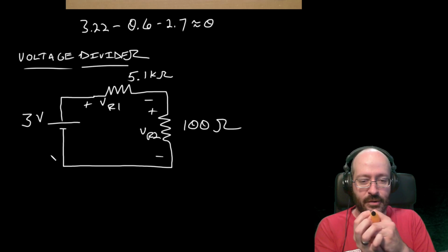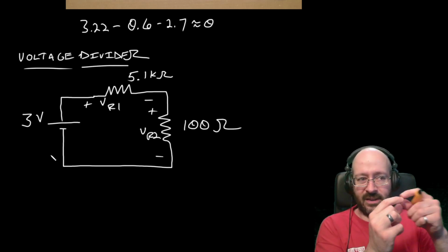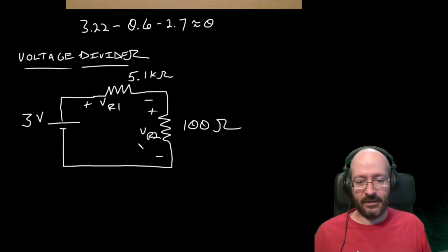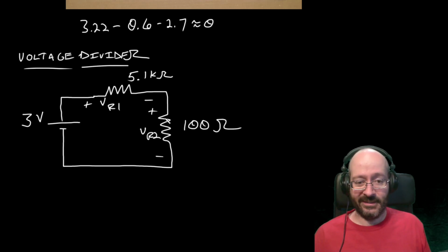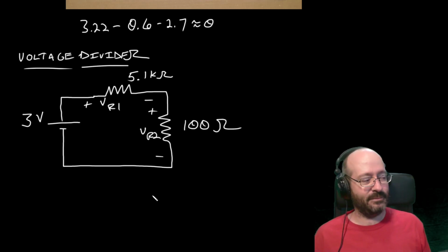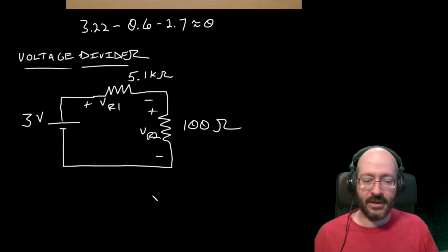Let's just think of it as a voltage supply and a resistance. And because of that, we can hook up another resistor to it. Okay, and if we're thinking of some big circuit as a Thevenin equivalent circuit, this voltage supply and resistance, and we hook up another resistor to it, we end up with a voltage divider, and it looks a lot like this circuit, and that's why it just shows up everywhere. So it's kind of an important circuit in that respect.